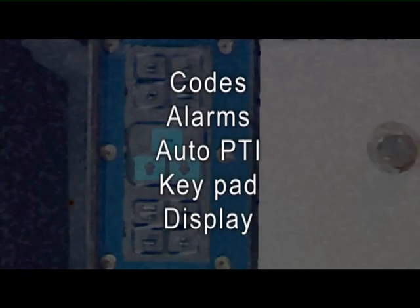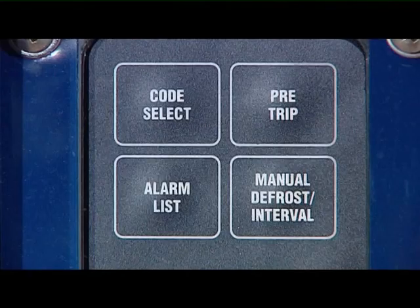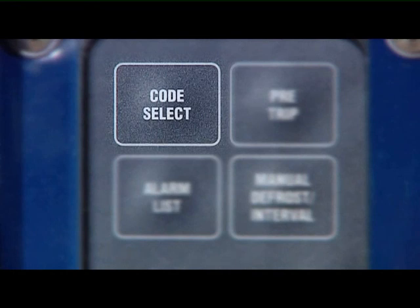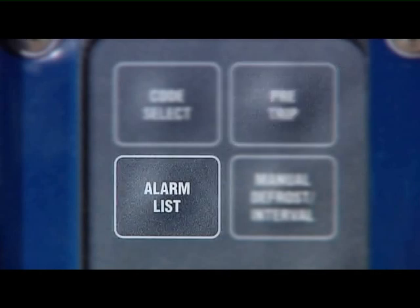Controller function codes, alarms, auto PTI, keypad and display. Keypad. The keypad consists of 11 buttons which allow the user to get information from the controller. The code select key gives access to the function codes. The pre-trip key displays the pre-trip selection menu. The alarm list key displays the alarm list and clears the alarm queue.